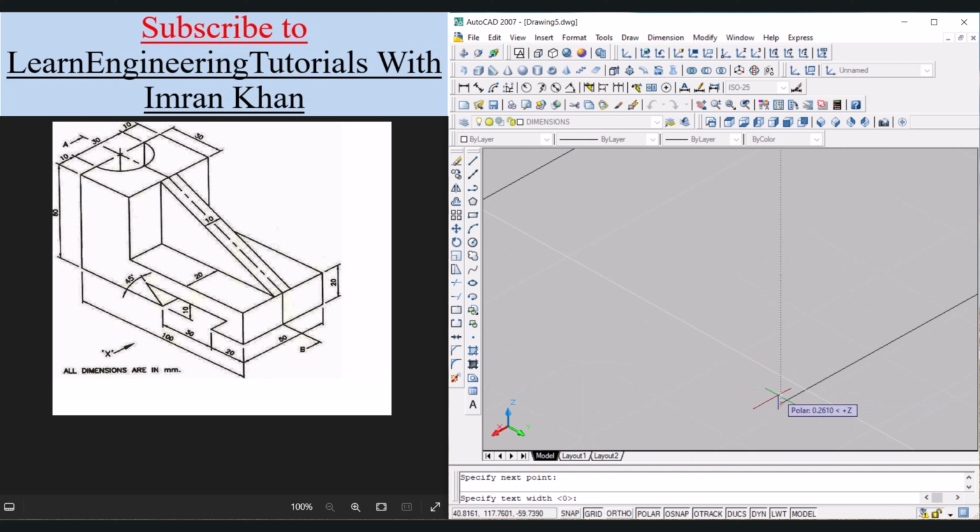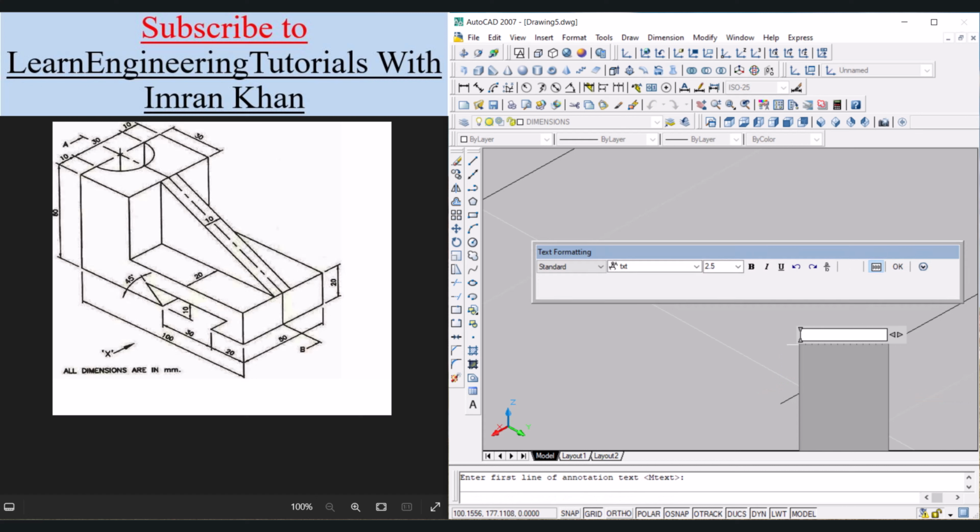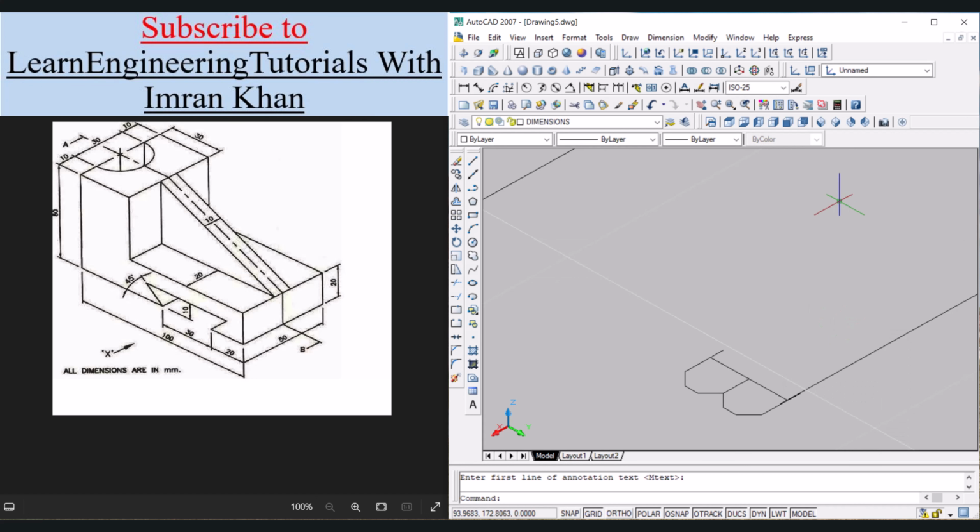Now we have to add the text width. Let it be 2, enter, and we have to write the M text, press enter. Now here we have to write, for example, B, and then click on OK. So now this B is written in the horizontal direction, or from the top view it can be seen. So we have to rotate this, right? So click on this B and delete it.